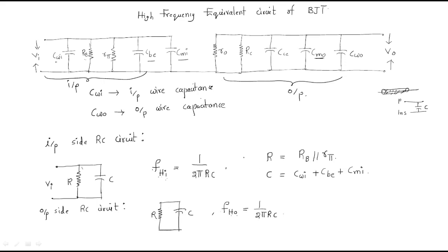Here also observe, we have two R's. In order to get the output side R value, RO and RC are parallelly connected. So RO parallelly connected to RC.